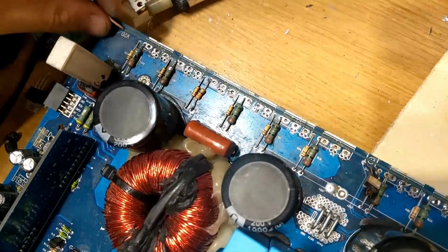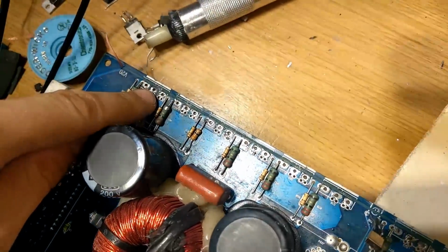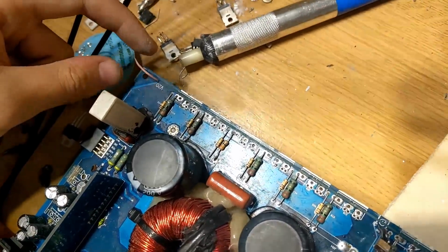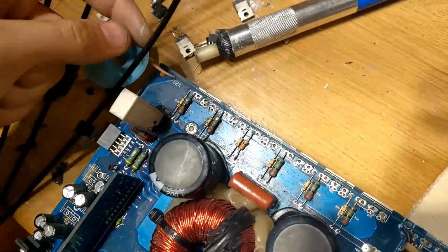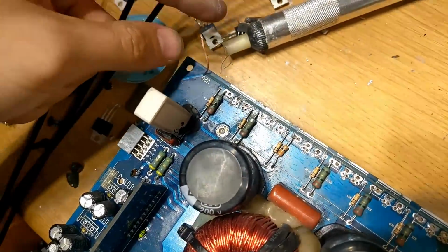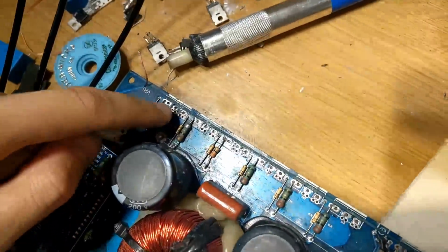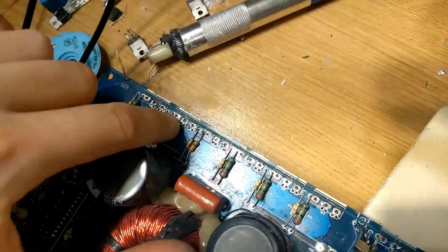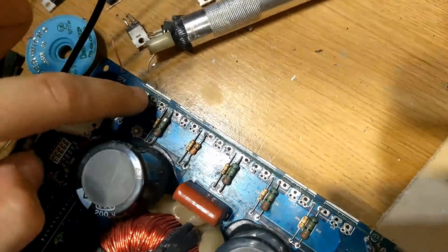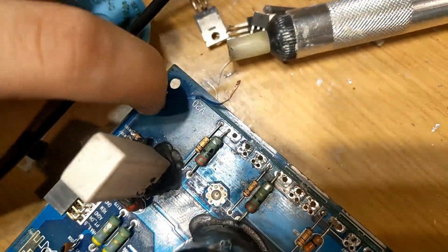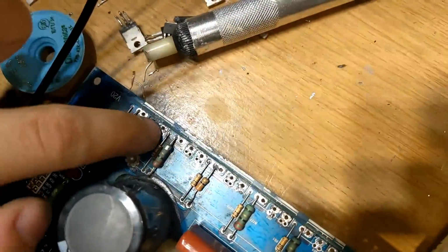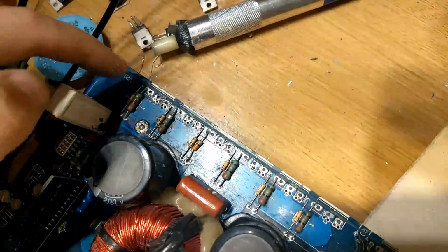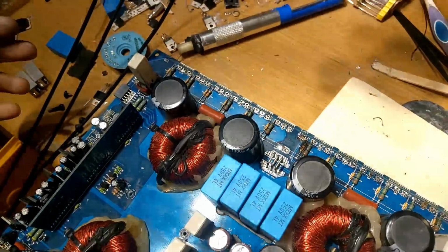I don't like how close this trace is because you've got high voltage on these high side MOSFETs here, really high voltage, and you've got switching as well, which is noise inducing, and then you've got this trace carrying the 12 volt auxiliary rail right next to these pads, and I don't like that. But what happened, this amp has been repaired before, and when the MOSFETs are being replaced, some of the insulation from the trace was not present by these pads where the soldering iron has rubbed over them in the past multiple times. I think it's probably been repaired a few times.